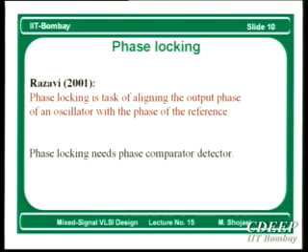So this is the basics of a phase lock loop. It is a loop which locks on a particular phase, and because phase and frequency are not independent, you cannot change phase without changing frequency, since frequency is the derivative of phase and vice versa. Therefore, effectively you are able to do frequency locking also, meaning your frequency will also be set on the reference frequency. That is a very interesting result: not only can you reconstruct the signal, but you can reconstruct it with a well-defined frequency.